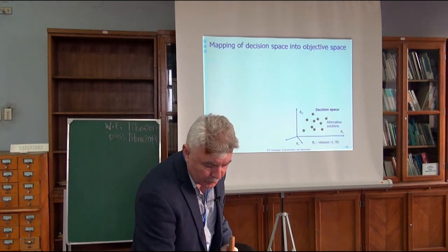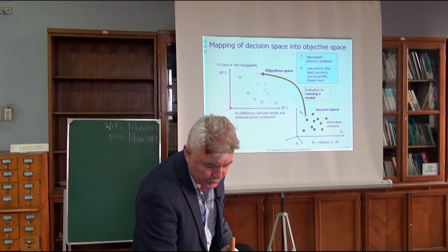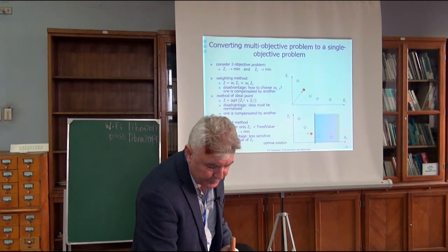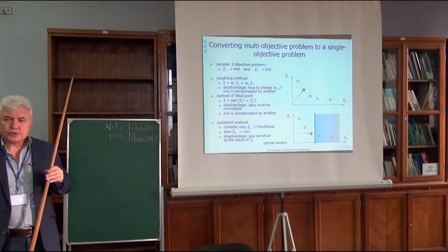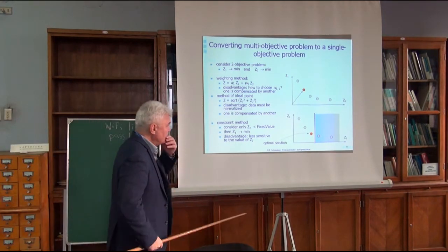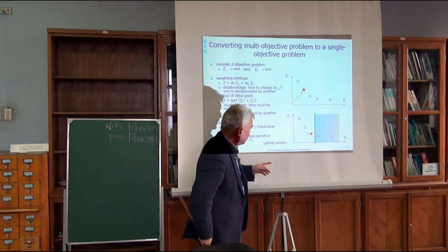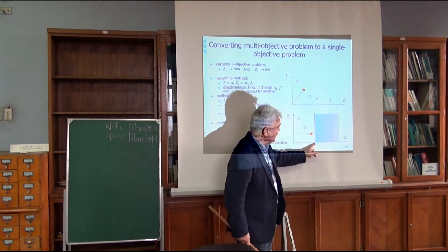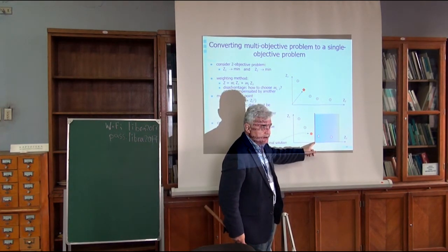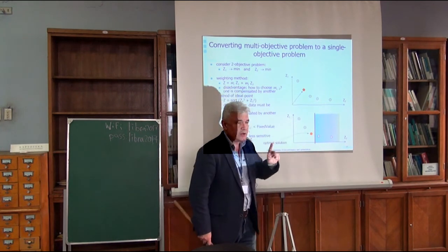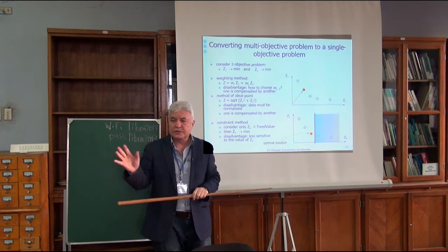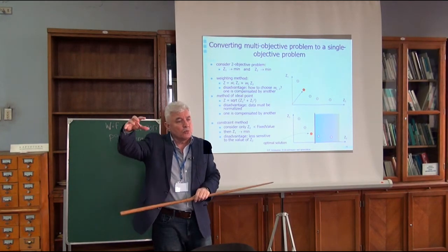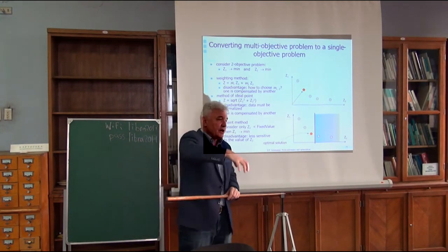So what we did, again, we showed this already, so it's the same picture. And what we did, we simplified the problem. We switched to a single objective optimization problem and used dynamic programming. And we said, okay, if navigability for 7 months is above, sorry, if the water level in the river is above 2 meters, we don't care then. Then any solution would do. So we moved one objective function into a constraint.